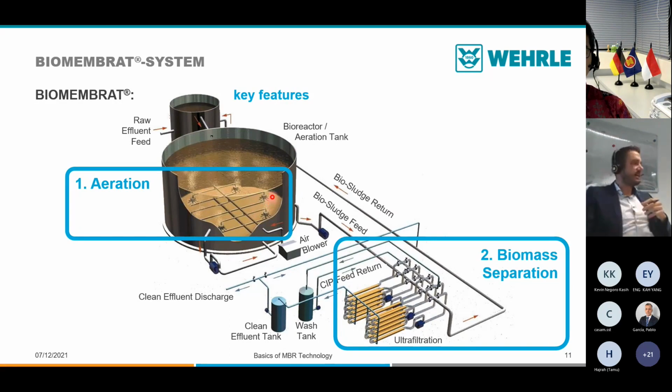And also they can handle MLSS concentrations up to 20 grams per liter. Also, the external membranes can run up to 20 grams per liter bacteria concentrations. A submerged membrane usually is limited to 10 grams per liter. That means we can bring 2 times more bacteria mass into our system, so we have a much more compact reactor. We have a much more compact reactor since we can run it up to a 15-meter water level. That means we have a really compact plant with an extremely efficient oxygen system, which saves energy. And we have an aeration system installed which is completely maintenance-free.